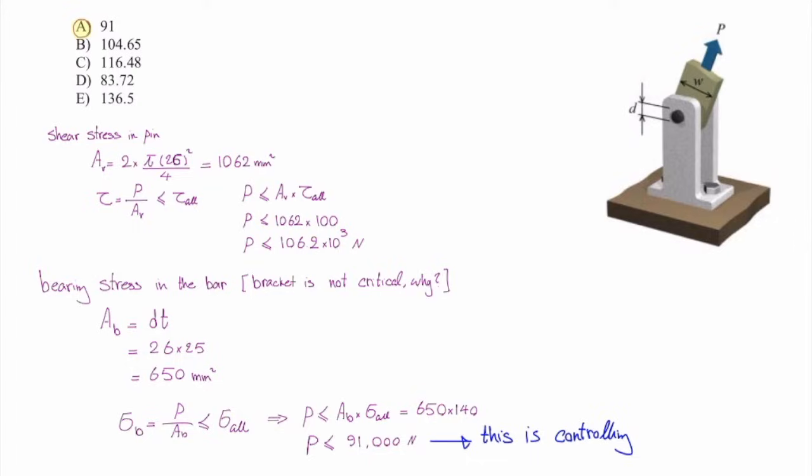This is what I discussed, and there are, I guess, 3 videos on YouTube. Let me show it here. This is the cross-section of that hole. If I consider the circumference when the pin is pushing toward that plate, I need to consider half of the circumference. But I'm considering along this line. So that would always be smaller than the circumference. So that's more critical. That's why we consider diameter times thickness in the bearing stress.